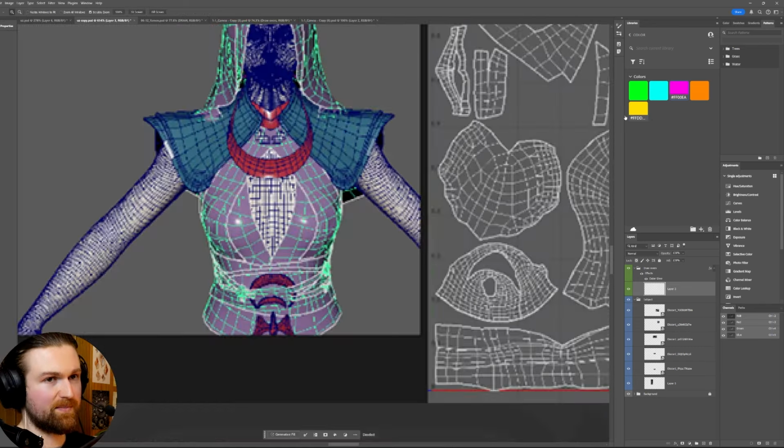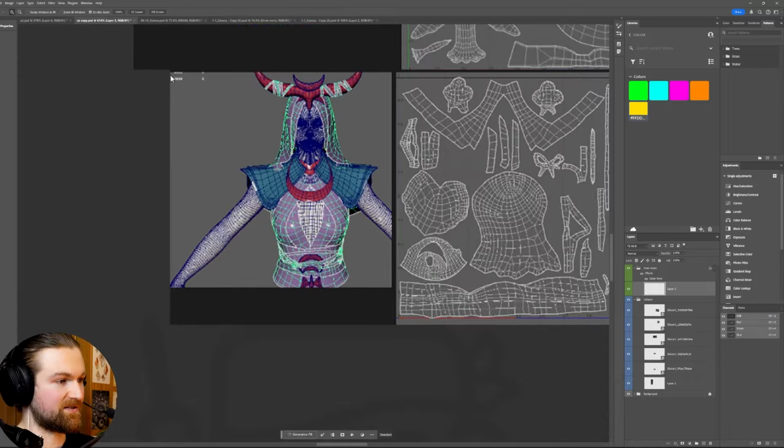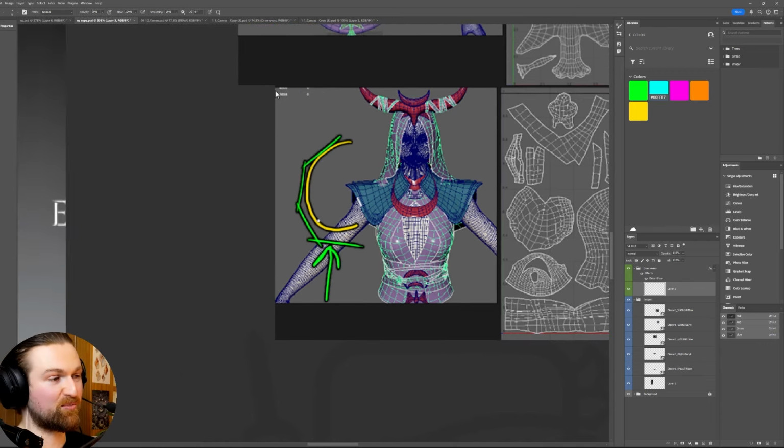And the same can be said for the breast area. Say, for example, from the edges, you might see these spikes hang out. With curved assets, let's say that's a curved high poly, the last thing you want is really low poly geometry and these jagged areas pointing out. It's going to cause a couple of problems, without getting too deep into it. You'll get some black artifacting when it comes to baking. The more accurate a low poly is to a high poly, the fewer artifacts you're going to have. That's always a nice feature. And then obviously we're not going to have these ugly silhouette corners.